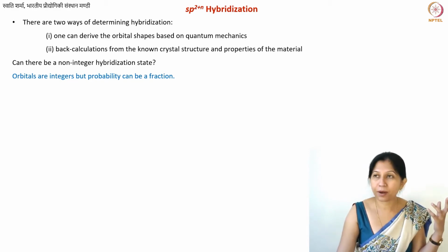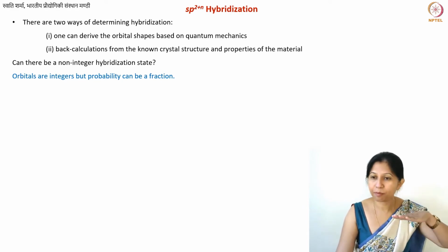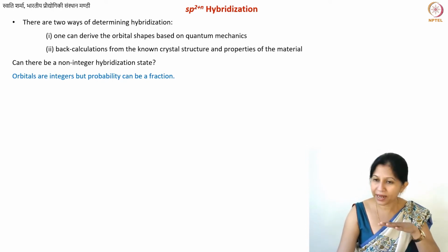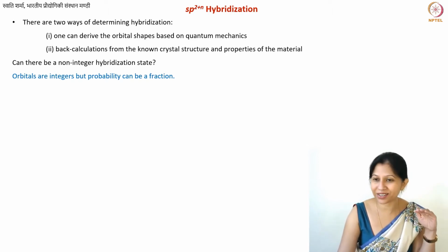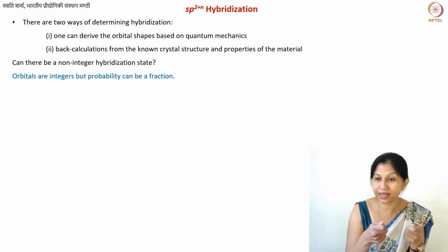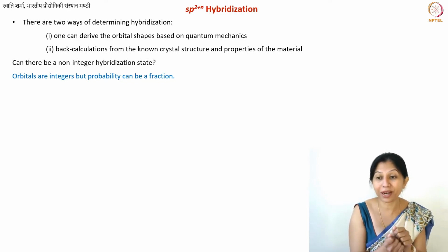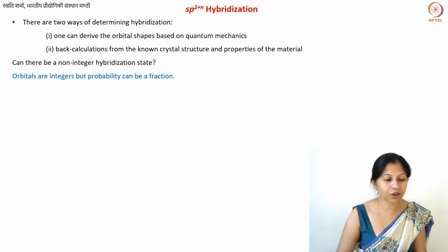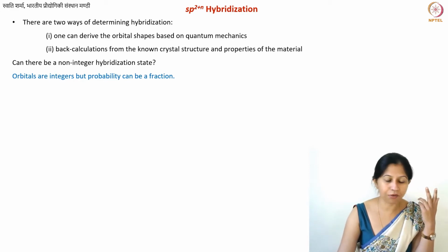Similarly, when you have a graphite crystal, you know that these planes, the basal planes of graphite, we will learn about the crystal structure of graphite in detail. The planes of graphite can slide on top of each other. You have this layered structure. So you know now that these layers within themselves, the single layers, are very strong. But when they are stacked on top of each other, the bonding between them is not very strong. So this already gives you an idea of the bonding.